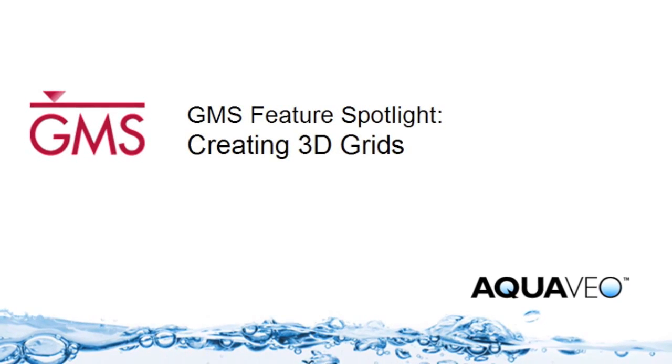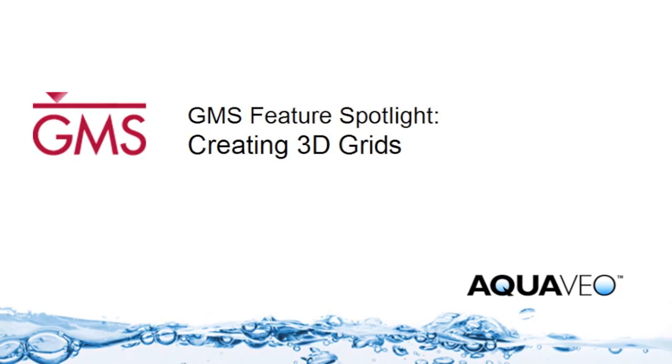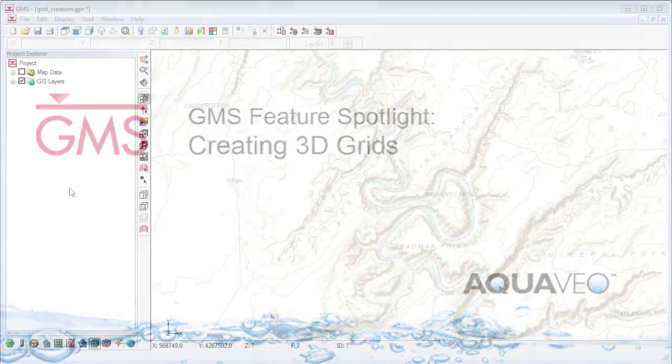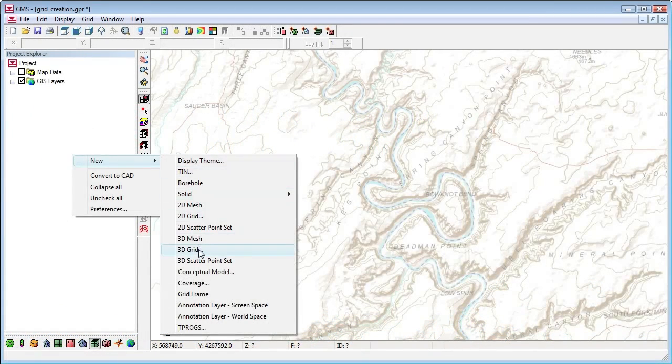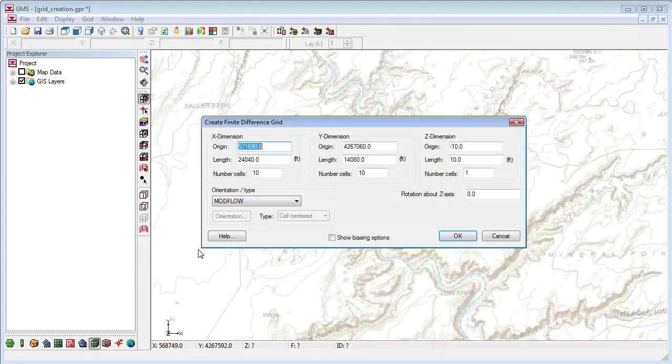GMS provides several different options to create 3D grids for use with ModFlow models. The quickest way to create a 3D grid is to right-click and select the New 3D Grid command. This opens the Create Finite Difference Grid dialog. You can specify the origin, length, and number of cells in the X, Y, and Z directions. You can also specify a rotation about the Z-axis.